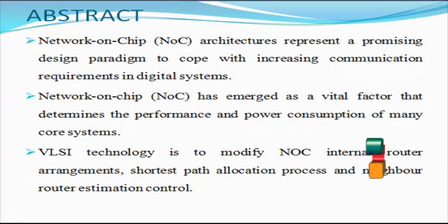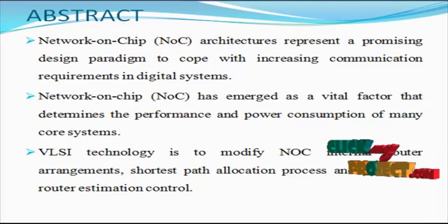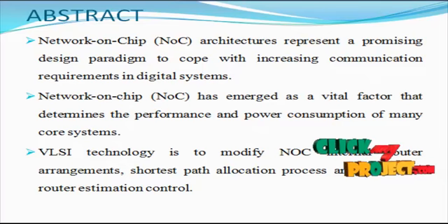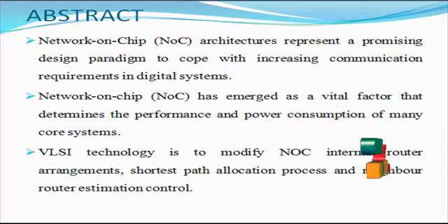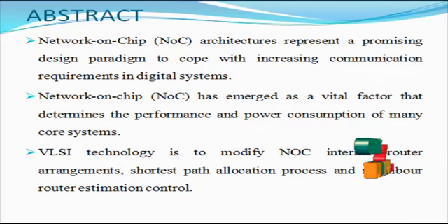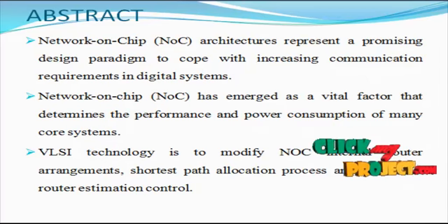Therefore, exploring different methods of IP planning for performance and temperature distribution is an indispensable topic for 3D NoC. From the above analysis, this paper chooses the torus topology with a shorter interconnection radius as the 3D external topology, and a deadlock-free routing algorithm to break through the 3D mesh performance fault.